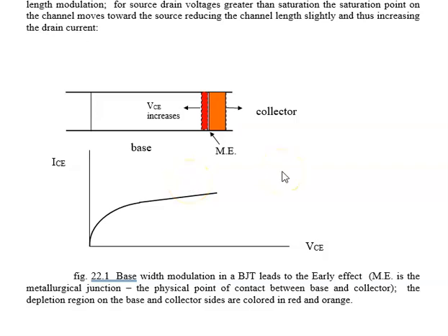Okay, so that is kind of a blast from the past for the BJT. And of course, if we have different values of forward bias, we would have different curves here, and all of these curves end up, I probably should have shown this explicitly, in the quote-unquote Early voltage, which we would like to make as large as possible. 60 volts is pretty reasonable, 60 or 80 volts.